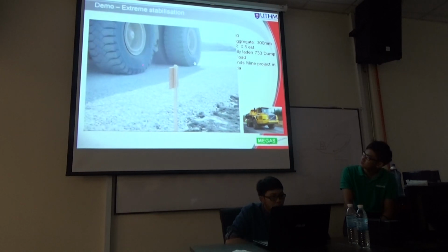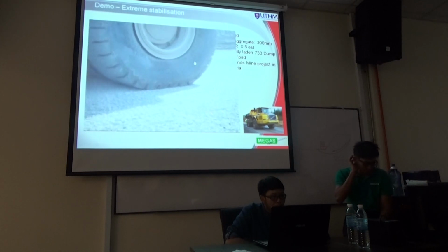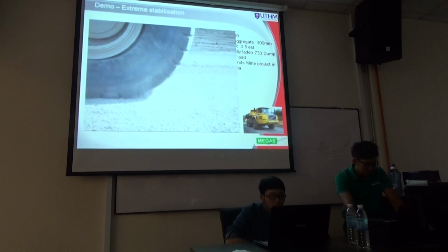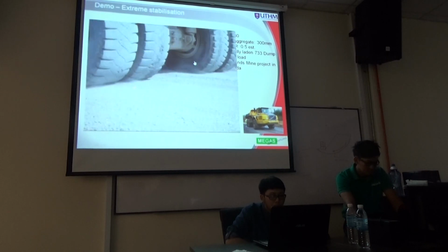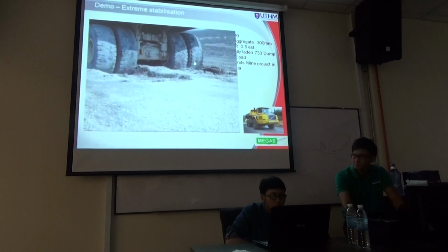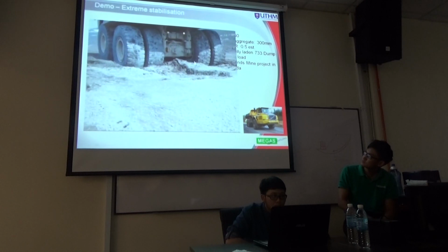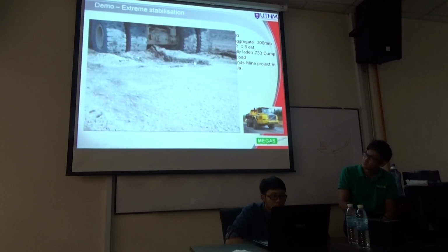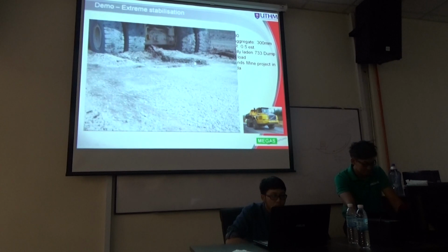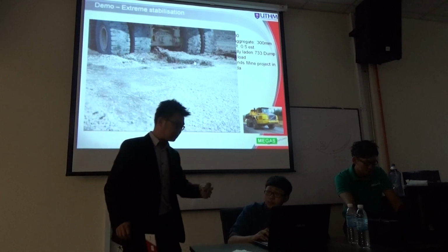Perfectly okay, it runs smoothly. If you stand at the side here, you can feel the vibration. This is when the truck goes into the section where there's no stabilization. We have big rutting, it mixes all the stone and the subgrade material together. Once it mixed together, the property of this imported material will change. It becomes a lousy material. So the problem will become worse and worse. Okay? So this is just so that you have a view.